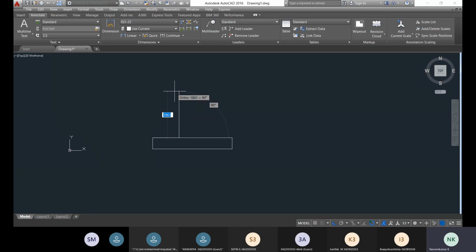So what is the height of the wall? The height is split into 3 meters and 1.75 meters, because the reinforcement detailing for the upper 3 meters is different from the reinforcement detailing for the bottommost 1.75 meters. So you have to draw the wall in two segments. The first segment is... If you convert the 1.75 meters into mm, what will you get? Answer me.